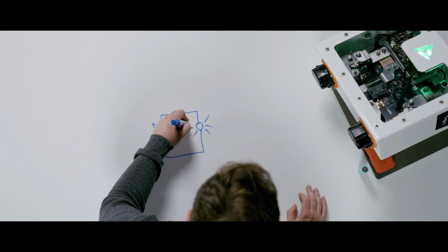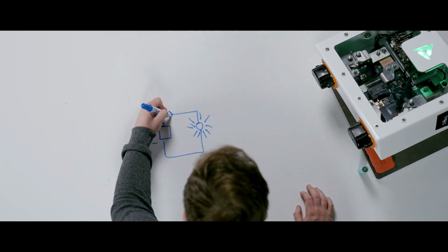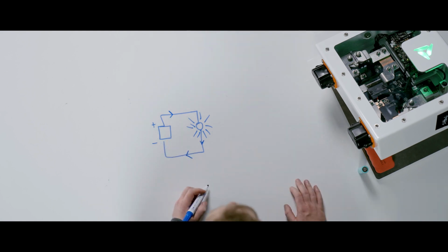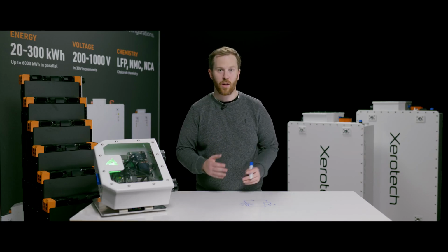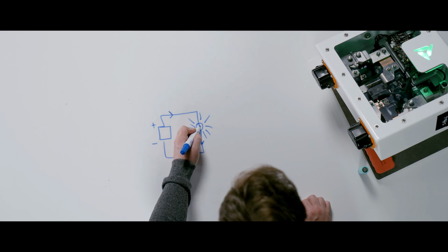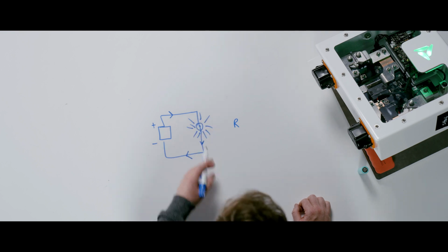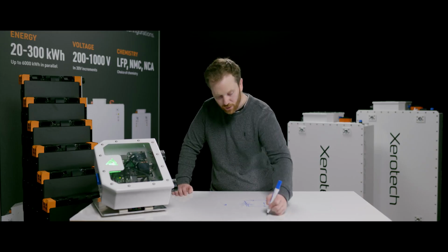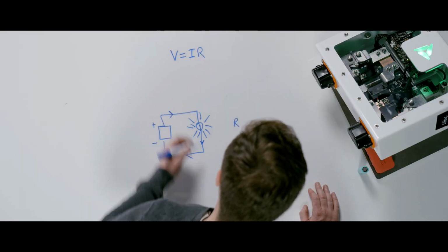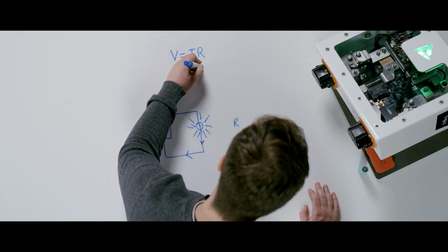and this is not exactly an electrical schematic, but what it's doing here is it's creating a flow of current through this light bulb and it's dissipating energy. So basically most traditional old types of light bulbs are just resistors. So this is a resistance inside of this light bulb here, R. And the amount of power that it's able to dissipate in generating light is going to be, the voltage is equal to the current times the resistance. And the power is equal to the voltage times the current.